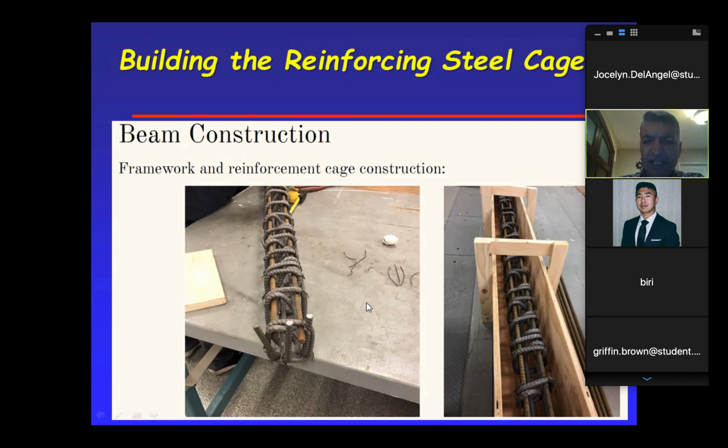And then we put the cage inside. See how we put the cage in, then we put this piece on top? So that's what we were talking about. We always had this here because I wanted to brace the sides, because the pressure of the concrete is a lot. I didn't want to risk losing the form, because think about this: this form is attached to the bottom only with some small screws from the bottom. And look how thick the wood is. It's not that strong.